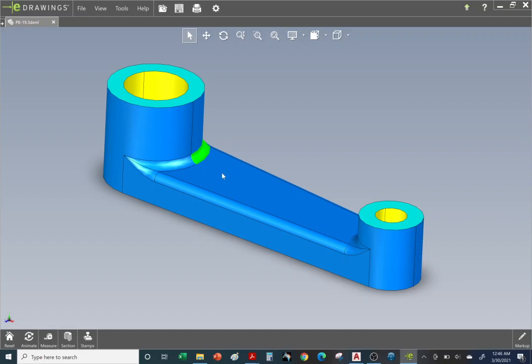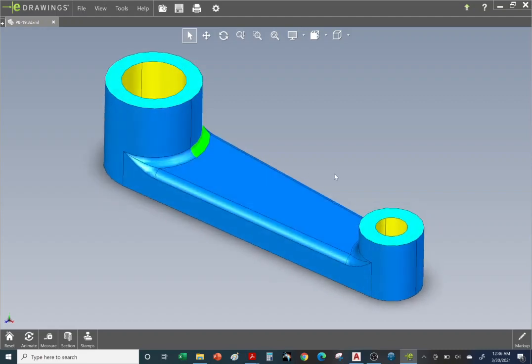But this piece needs to mate up to other parts. This is something that you commonly see on a car, for example. It can be something in the suspension, or a good example is a water pump. If you look at the old vehicles, like an old Chevy or old Ford, the water pump will have a rough texture to it because it's cheaper to cast it into a mold. Take it out, and once it's solid, it'll have the rough surface. And then you can come in and machine off the surface, so you have a nice, flat, planar surface.